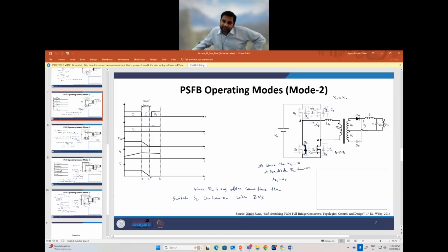Just see the current. In this case you just see the current. If you start seeing the voltage you will get confused. The current here is nothing but IL, and that IL will be reflected in the form of IP, times the turns ratio, so IL will be IP. That has to be there. That is the beauty of the transformer. It is just the L leakage which takes care of the voltage difference between the terminal voltage and the induced voltage.